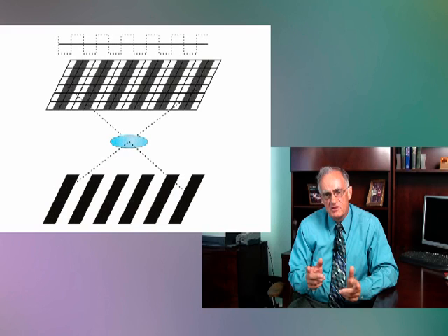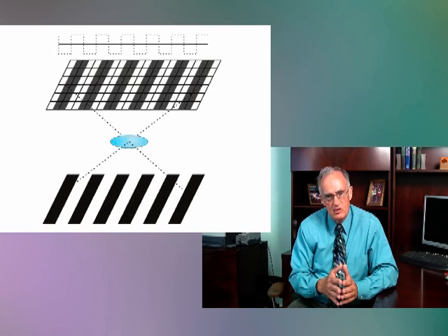However, if we move this target just a little bit, just half a bar's width to the side, what we get is a uniform shade of gray out of our vision system. This is a critical spacing called the Nyquist frequency or the Nyquist criteria. We really can't hope to resolve detail this fine or finer with a vision system.